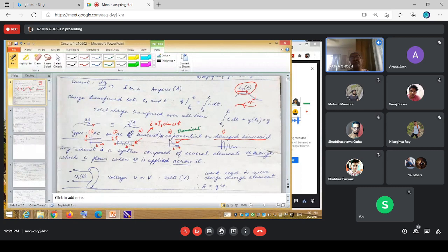You know about inductances or capacitances. So if you are withdrawing or switching off or switching on inductances or capacitances in a circuit, in that case you have the exponential currents coming in, transient, which last for a very small duration of time typically, and typically the current would go down to zero. Okay, so it is not in that sense truly a direct current per se, because it's dying out to zero, and in that sense we call this a part of the AC current group.